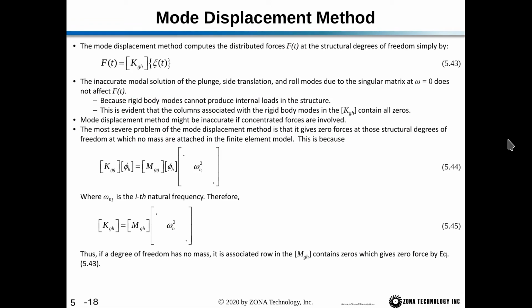So we'll first look at the mode displacement method. The mode displacement method computes the distributed forces F of t at the structural degrees of freedom simply by equation 5.43, where we have F of t is KGH times ξc of t.